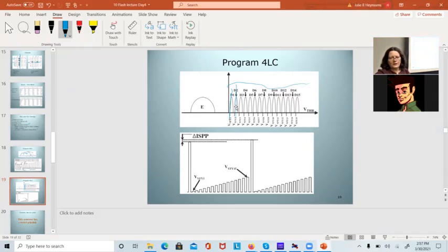I need greater accuracy, which is going to mean I'm going to have to do smaller steps on my programming voltage. Each step takes a certain amount of time, so it's going to take me longer to program it. This is why these are used on lower end devices, where I don't care about speed and I don't care about durability as much. They're going to spend more time in programming too, and the programming time with the large voltages is what's going to wear them out.